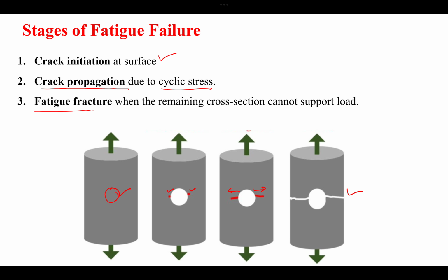In the first one, the crack initiates. It initiates due to the surface roughness or surface not being of good quality, or maybe the load is too much, so it initiates the crack. Then it propagates slowly, and finally it cracks.